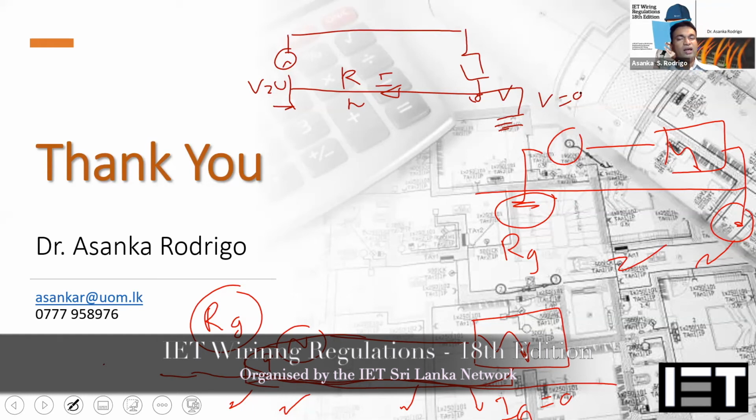Other than that, at the consumer level, I don't think there is equipment, and what exists is very costly. For example, you can put in a separate voltage regulator, or even an isolation transformer within your premises, and take the supply through the isolation transformer with the earthing connection. That type of thing can be implemented, but it will be very costly.